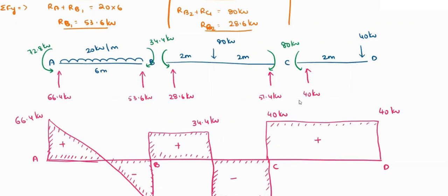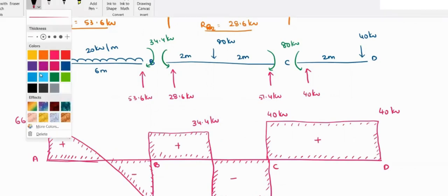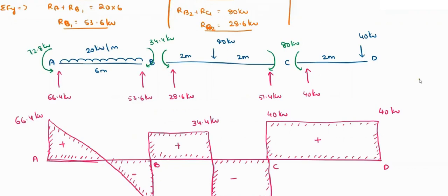So we can directly follow the sign convention, I'll just show you. Clockwise moment means it will be a positive shear, anti-clockwise moment means a negative shear. Here if you take a segment, when your arrow is heading upward and downward, and you take a section, this is left hand side and this is right hand side.